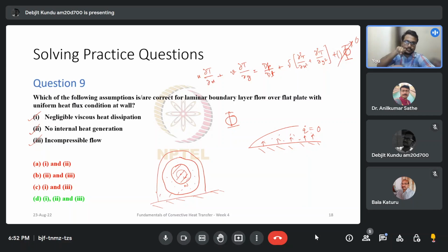This shaft lies within that fluid and is rotating with a very high omega. So in this case, what is the velocity? The velocity would be omega r at this point, and at this point it would be zero because of the no slip boundary condition.